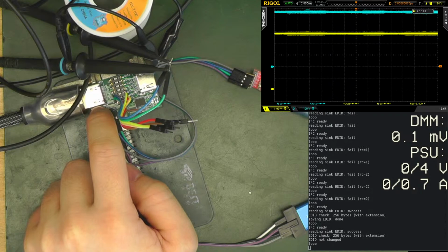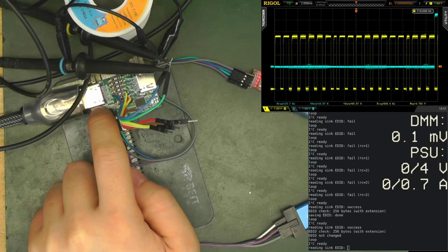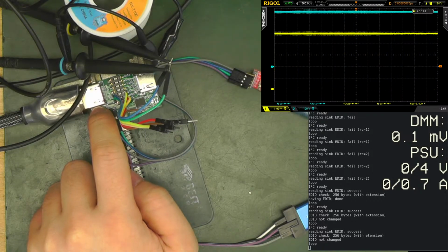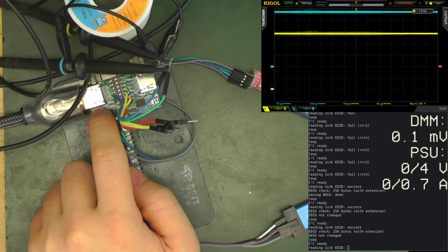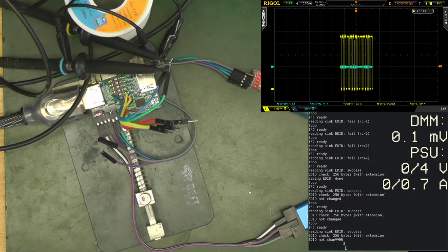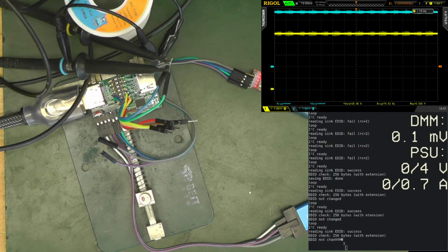The code works, but you see already the pull-up is at the limit here. The pull-up is still very slow, but it's because my design is flawed. But I2C now works even if I don't pull it up myself. So this is one bug fixed, and the bug is in my design.